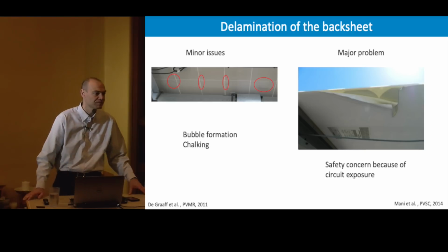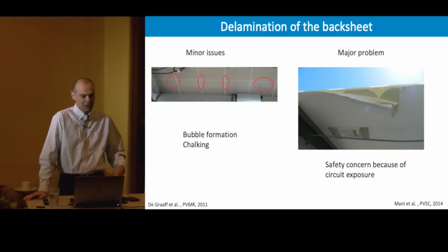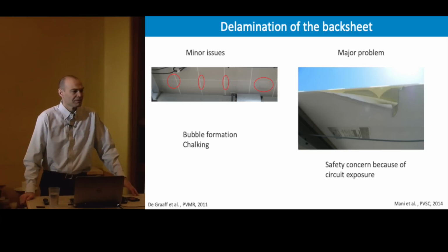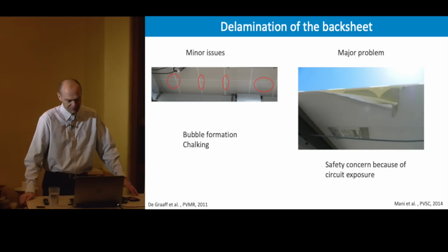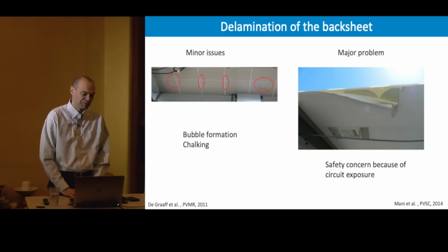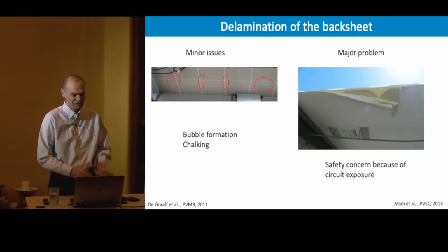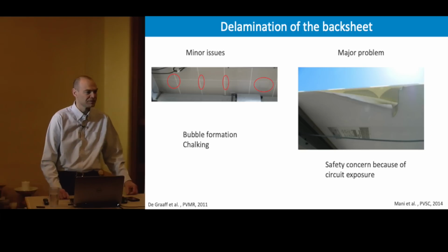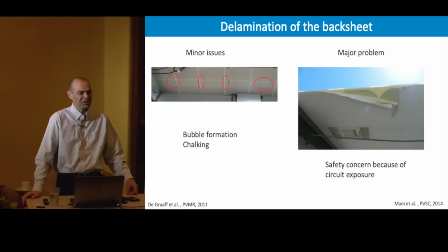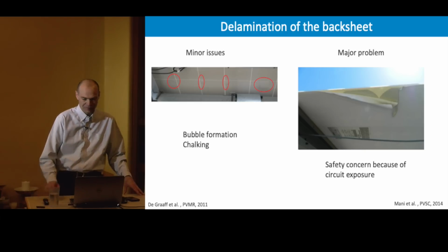And the pressure from the bubbles is caused by what pressure? Well, gas formation, so some chemical reactions happening in the module. In the laminations, not in the actual solar cell. Yes, in the lamination. This is what I was talking about earlier. Most of these failure modes have to do with the packaging of the module, not the silicon itself. And if we were to take a pin and pop the bubble, would that be no good? That would probably not be a good idea because now you have a hole and a pathway for moisture to get in.